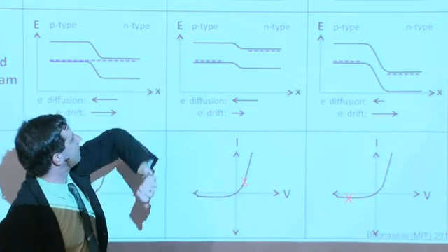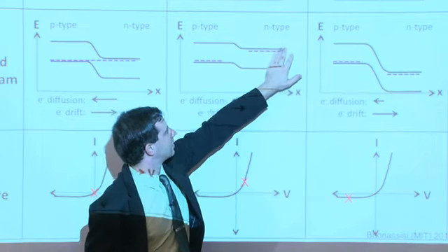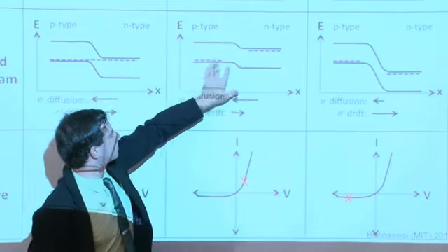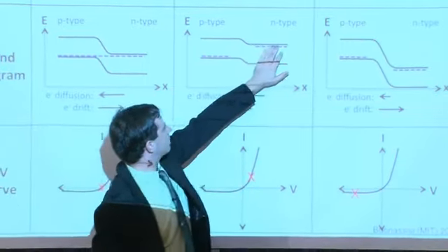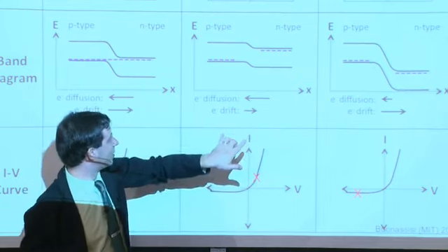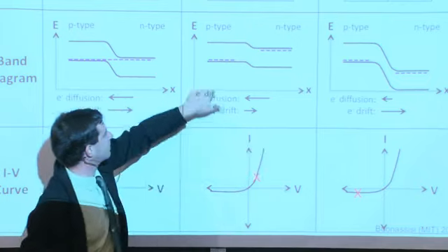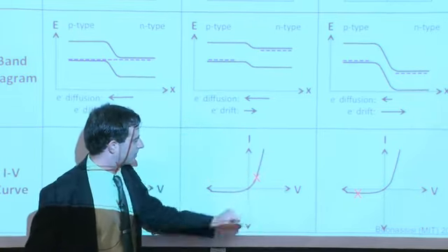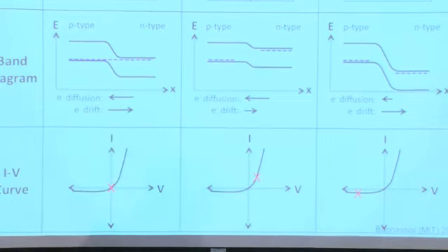Because if we imagine instead of having a battery there, we have a resistor, the electrons will travel from the N-type material through that external load to get to the P-type material where their chemical potential is lower, right? Because they'll desire to minimize their free energy. And as a result, they'll deposit that power across that resistor, across that external load, in order to get back to this other side, because that's the only path that they can travel easily, right? And so this entire curve shifts down. You have your red X somewhere in this quadrant over here, and power is flowing out of the solar cell